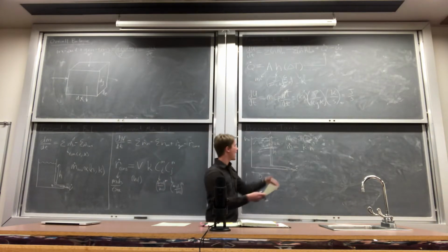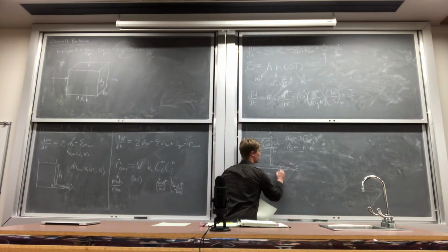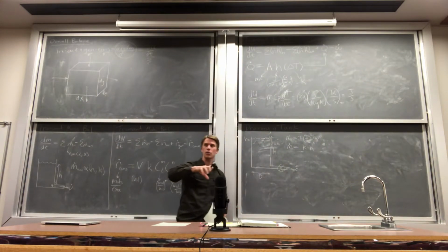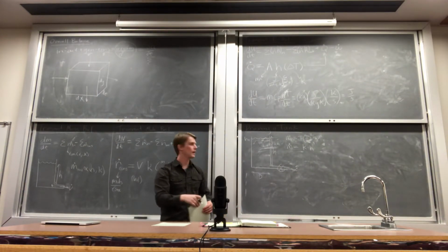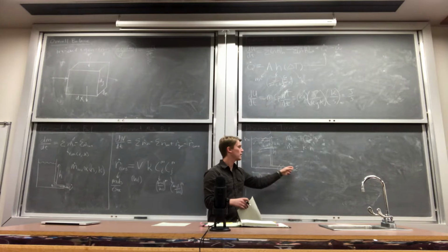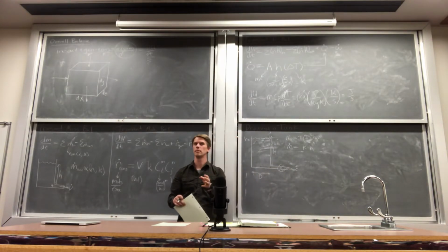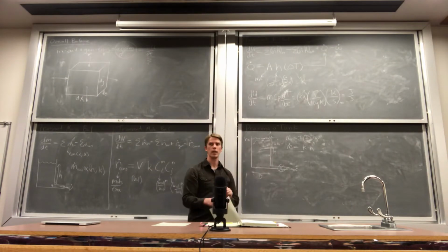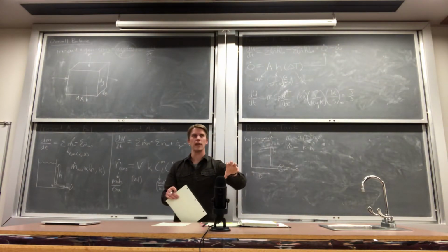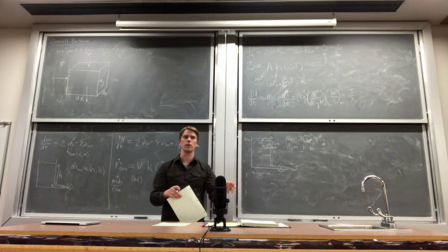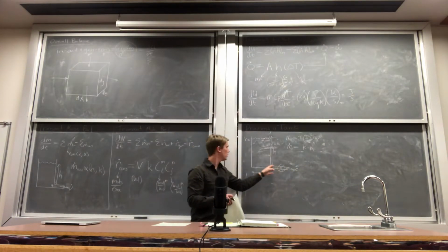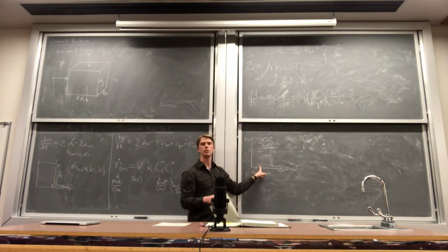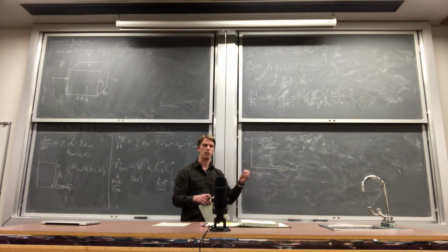So the higher the pressure difference, the more the fluid wants to get out. But if I add a valve into the process here, I can increase the pressure drop, meaning I need a greater pressure difference between the inside and outside to have the same flow rate. So based on how I build my piping here and how much pressure loss is associated with it, that controls how quickly my tank will drain. And what the valve is doing is varying how much pressure loss there's going to be. This is always going to be atmospheric. This is always going to be the pressure associated with hydrostatic head. And that's how we determine how quickly things will drain.